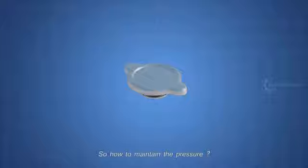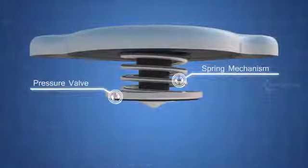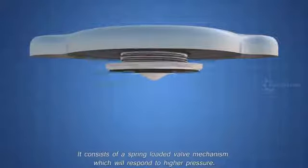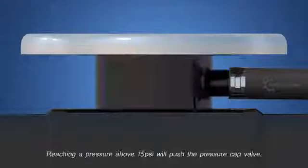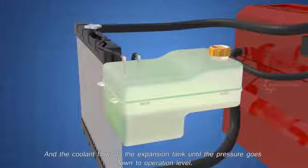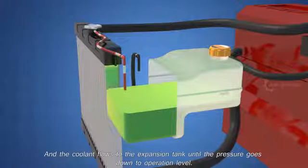Heating liquid inside a closed system always builds up pressure. So, how to maintain the pressure? Here comes the role of the radiator pressure cap. It consists of a spring-loaded valve mechanism, which will respond to higher pressure. Reaching a pressure above 15 psi will push the pressure cap valve, and the coolant flows to the expansion tank, until the pressure goes down to operating level.